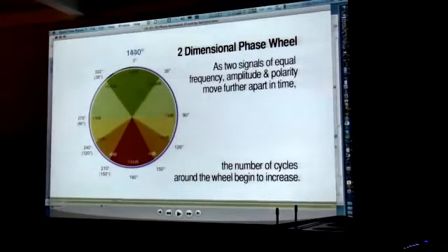But can you tell me what frequency has a time period of 0.25 milliseconds? 4K. So if I play a frequency sweep, then during the sweep the phase will be increasing, and exactly at 4K it's one cycle. At 8000 Hz is 2 cycles, at 12,000 Hz 3 cycles, at 16,000 Hz 4 cycles, and at 20,000 Hz it's 5 cycles.